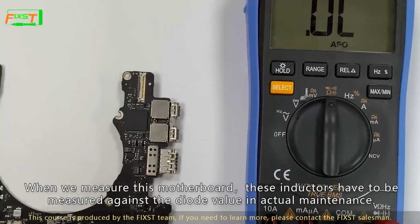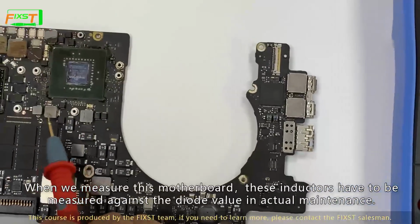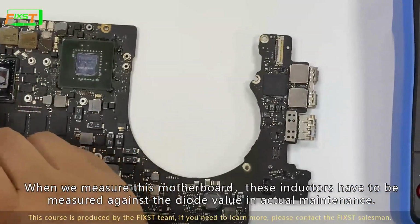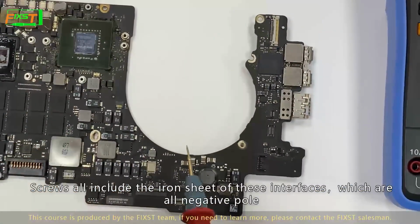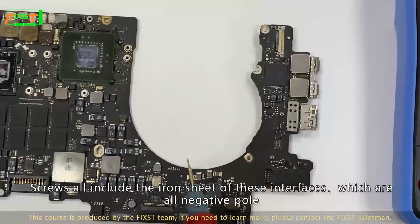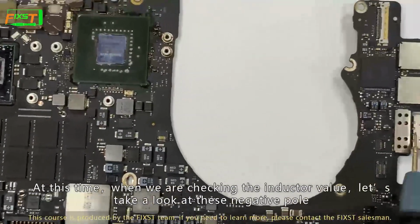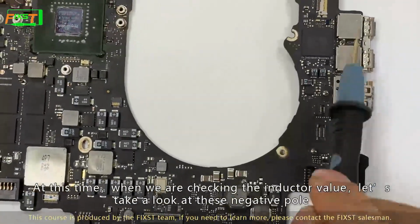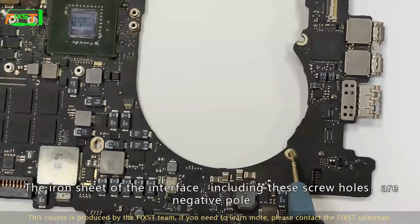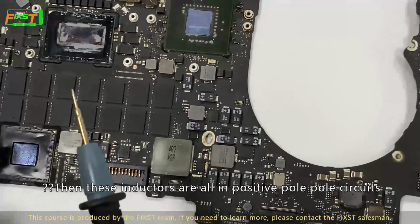When we measure this motherboard, these inductors have to be measured against the diode value in actual maintenance. The screws, including the iron sheet of this interface, are all negative pole. The iron sheet of the interface, including the screw holes, are negative pole. Then these inductors are all in the positive pole circuit.